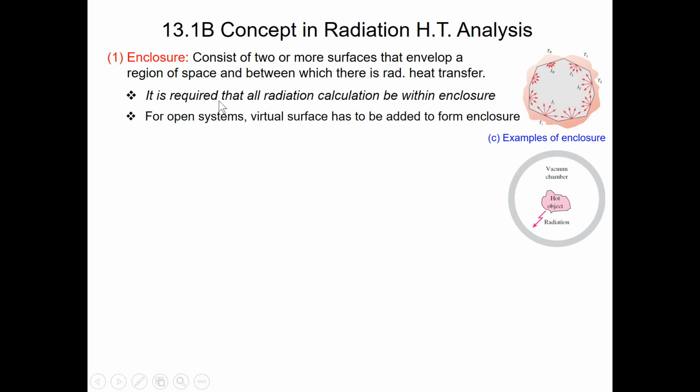It is required that all radiation calculation must be within the enclosure. Therefore, for some open systems, a virtual surface has to be added to form the enclosure.